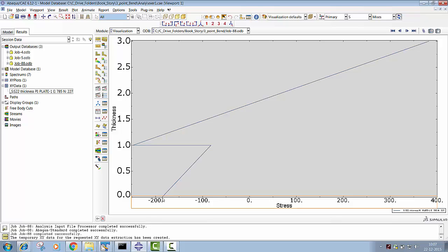So it is in compressive load, that is a compressive bending stress. Here it is somewhere around minus 180 MPa as a bending stress value, and there will be a linear transition up to this point, and at this point there is the end of the aluminum layer, and there is a step change in bending stress value for the steel due to the change in the modulus.